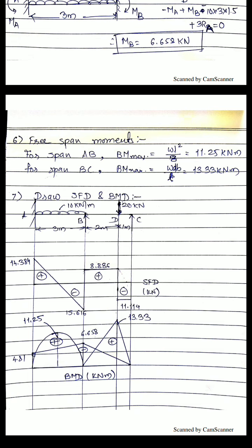It is also drawn in the positive direction. So if you join these three values, we know that the moment at point C will be 0 because it is a simply supported end. Okay, so you have to join these three ordinates with simple straight lines. Now you can see this particular area will be a positive area, and these two values are negative areas, and the remaining areas just cancel with each other.